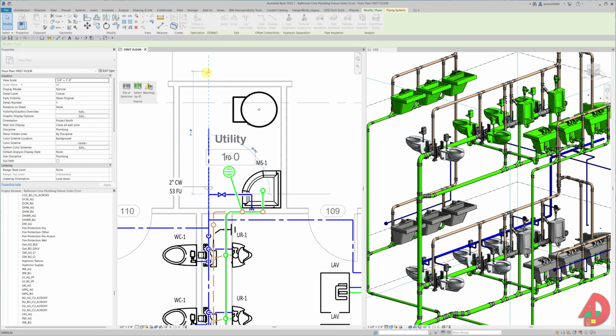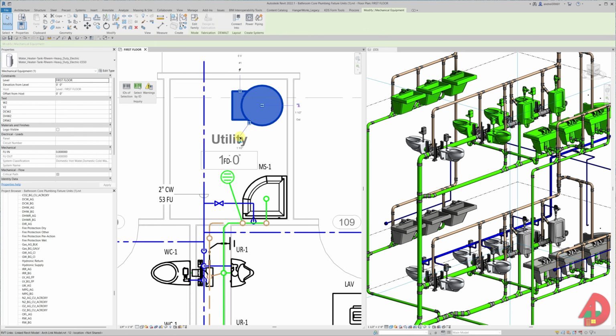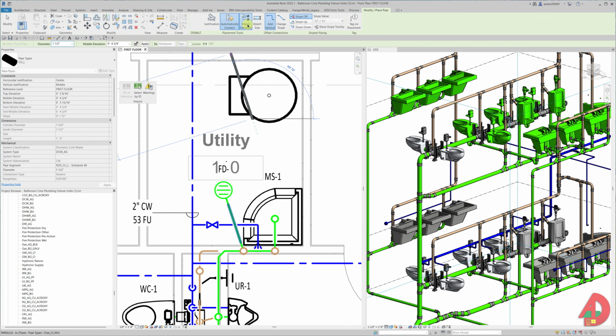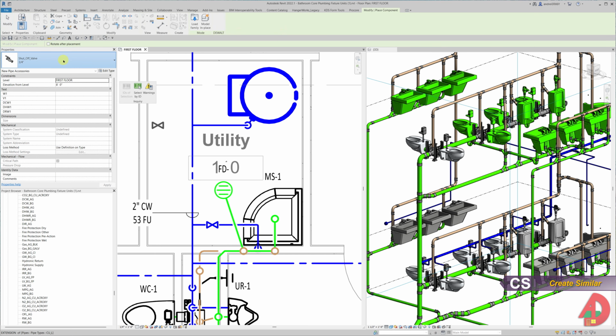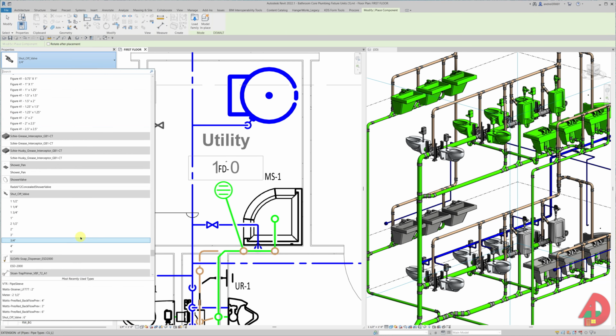After selecting the water heater, I can click on the cold water connector. I need to make sure I come at the connector elevation and size. I can draw a short line and then change the elevation to 8 so I can match the main. Also, I will add a shut-off valve for the water heater.